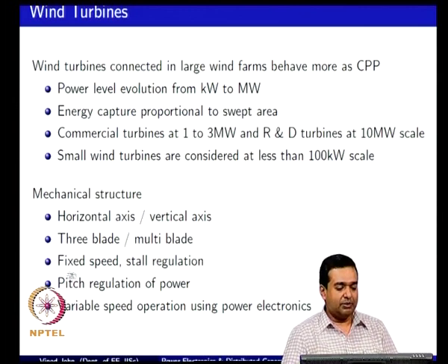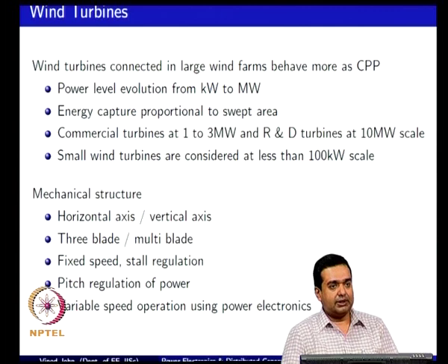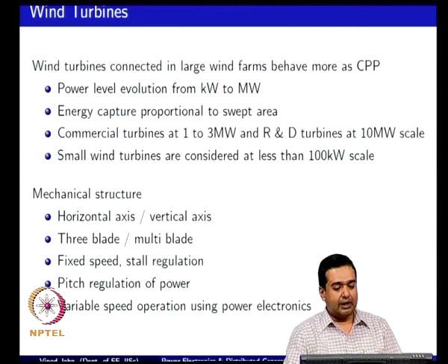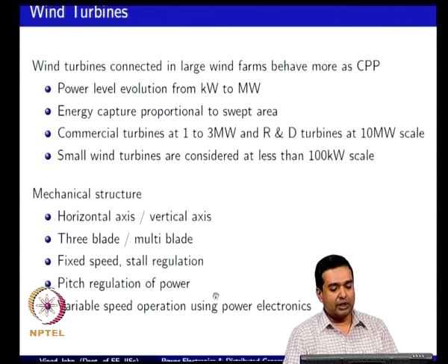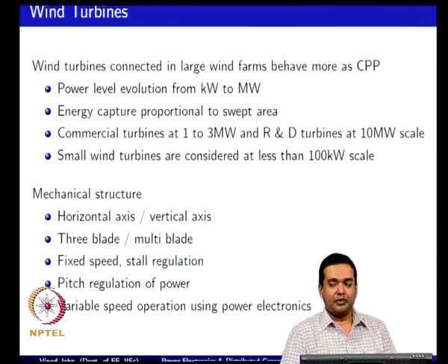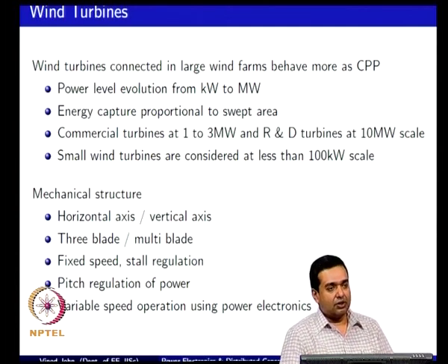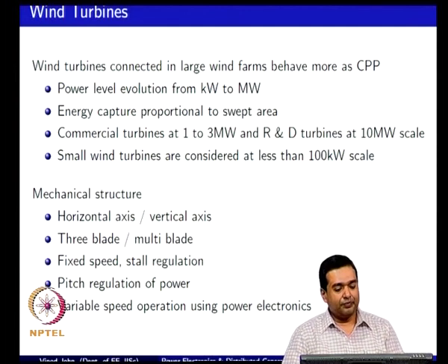What it means is that the speed would be dependent on the grid frequency, the motor that is connected, and the gearbox, and the limitation of power would come in by the design of the blade. So, for example, if the wind power becomes more, the blades were designed to stall rather than capture the increased speed of the wind. So, they are called a stall regulated turbine.